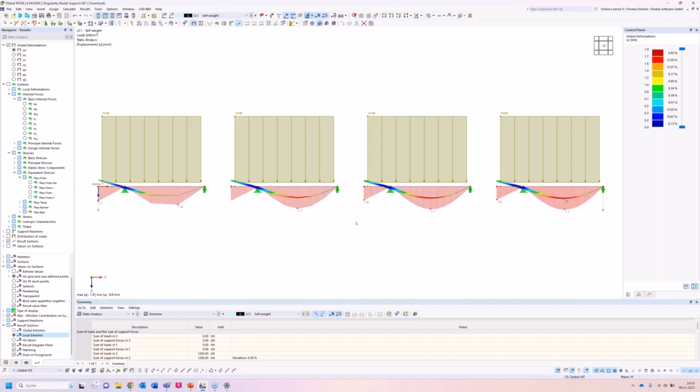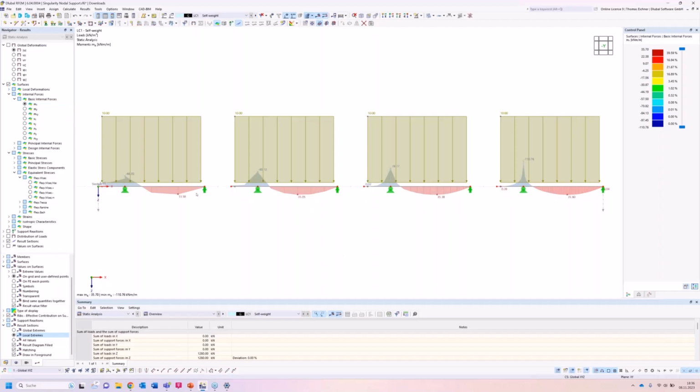There's also a different method, as mentioned in the beginning. We are now working with the deformation method. If you take the other method, the unknowns are not deformations, but forces. So also the singularity meaning changes. But right now, and for almost all programs, you will have the problems in internal forces. So we go again for the basic internal force mx. We can again see here there's a jump, there's even a jump.